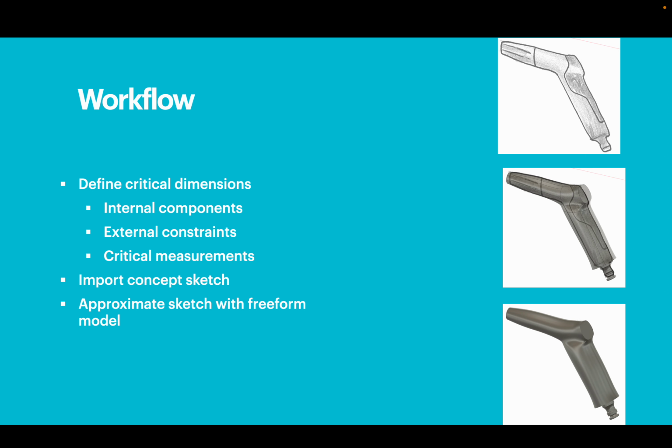When you do this kind of thing, your product, of course, will be driven by some important characteristics. Let's say you make a hose adapter like this. Of course, your outer dimensions are driven by the size of the handle. It cannot be infinitely large. Very often, if you make tools or anything else with electronics or something inside, of course, you need to fit that inside, so it cannot be infinitely small either. So it's a good idea to have those things that drive your design in your model before you start modeling, if that makes sense.